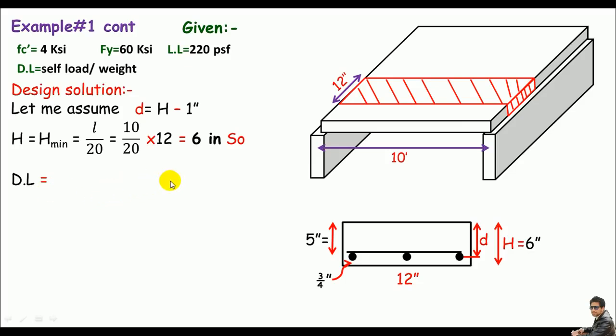What's the unit weight of RCC? Remember, it depends on the mix and the steel, okay? If the steel in the mix is normal, of course, the unit weight may be just from 145 to 150 pounds per CFT. So I'll take, this is of course RCC, so I'll take 150 as the unit weight, right? 150 pounds per CFT. So 150 times bh.